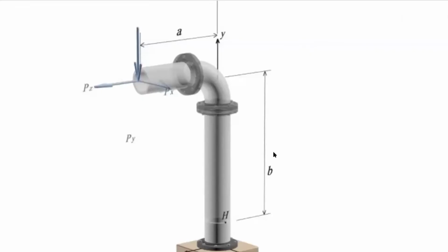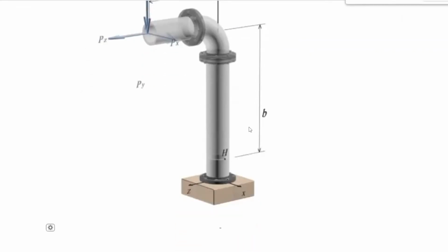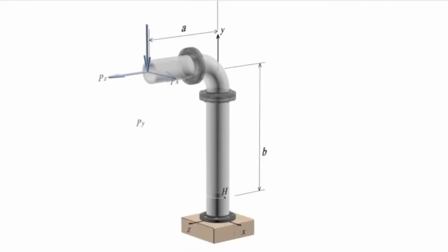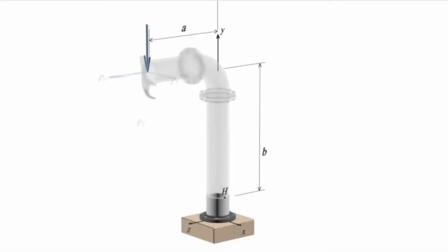All right, now we are focusing on the force in the y direction. In that case, again, we have to move this force by distance of A to the y-axis, but the type of moment produced by this move would be different. Put the hand downward along the direction of the force and face the palm toward the direction where you are moving the force. The bending moment would be about the positive direction of x. So the bending moment would be Py multiplied by A, and the sign of that would be positive, okay?